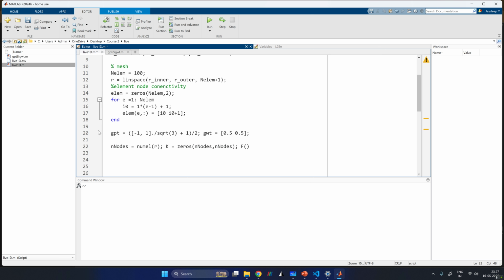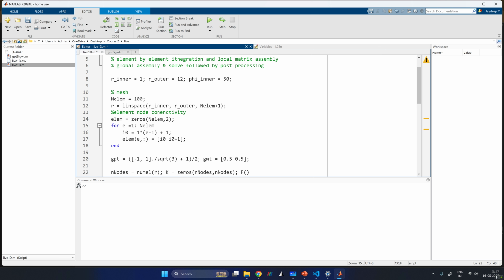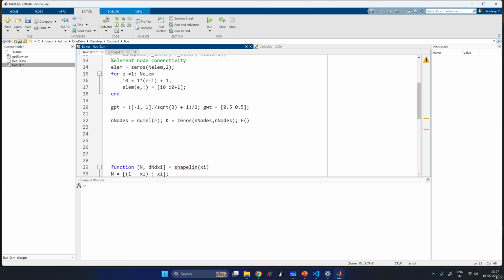So this is basically if your number of elements are 100, so number of nodes are 101. So stiffness matrix will be 101 by 101 because you are writing the bilinear form there, and the force vector is just the linear form, so that will be 101 comma 1. So 101 rows and 1 column. So we have initialized the global variables. So now let's start off with the assembly. So let's run a for loop over all the elements.